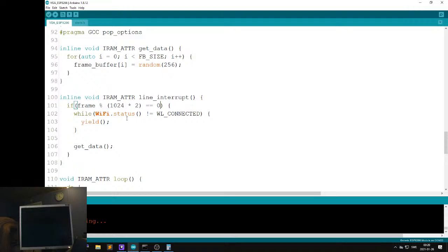Yeah, I should change this back to be a frame interrupt now instead of a per line interrupt, because we're guaranteed to lose the sync anyway. What's the point of running the interrupt so many times in a row?